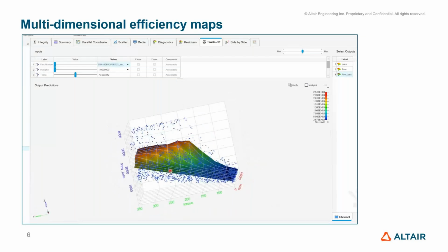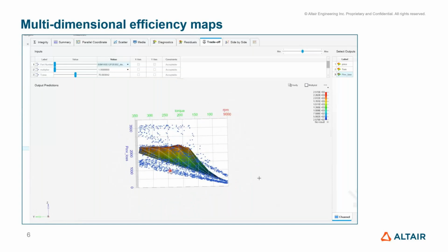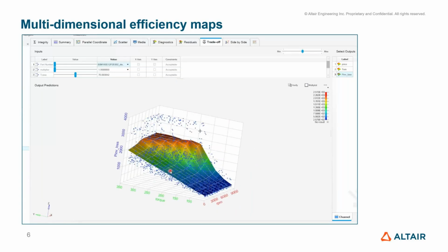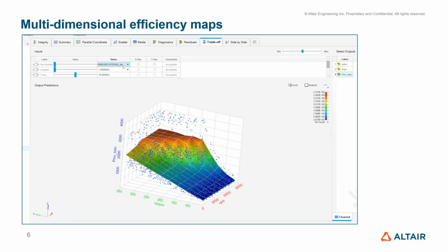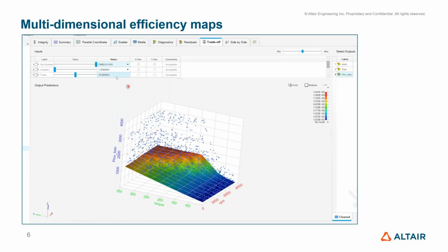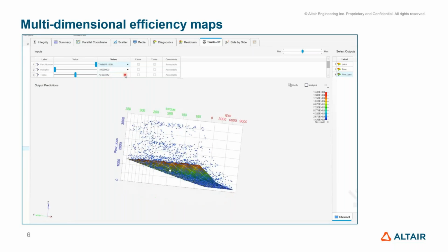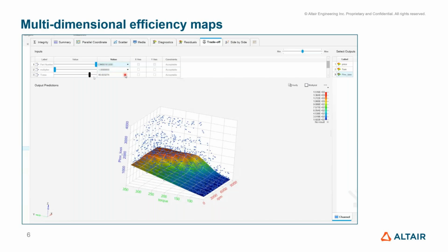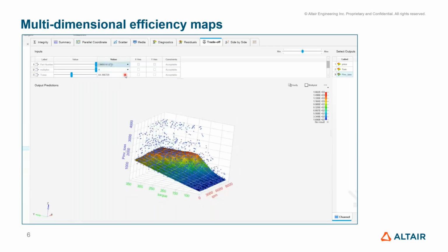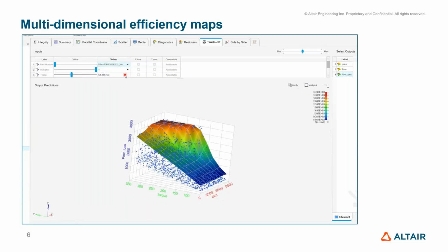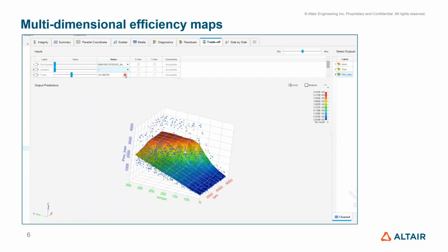And you see that the points are distributed in three different categories because we have different semiconductors. For example, there's a drop-down list where you can change the semiconductor and see exactly how the losses change. You can change the case temperature, which directly couples with the cooling of the inverter. And you can also change the gate resistance multiplier. The gate resistance is a trade-off between losses, switching losses to be more specific, and EMI.